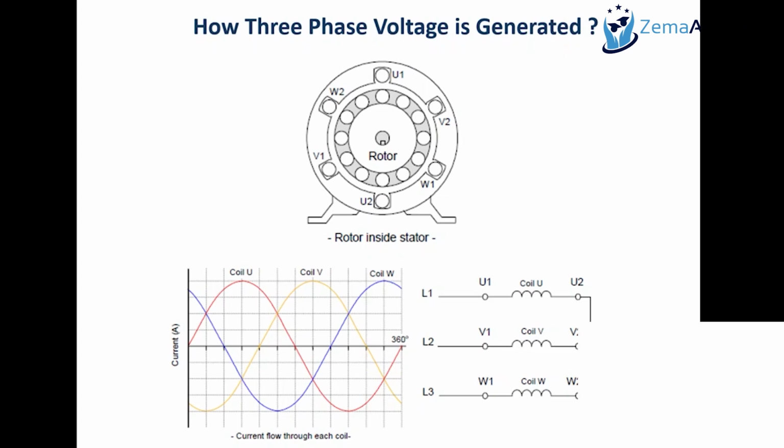If you were to have a 4-phase system, you need one more conductor to transfer that phase of the power, and this will incur cost to the consumers and to the supply companies. So the 3-phase system is one of the cost-effective ways to transmit the power, to distribute the power.